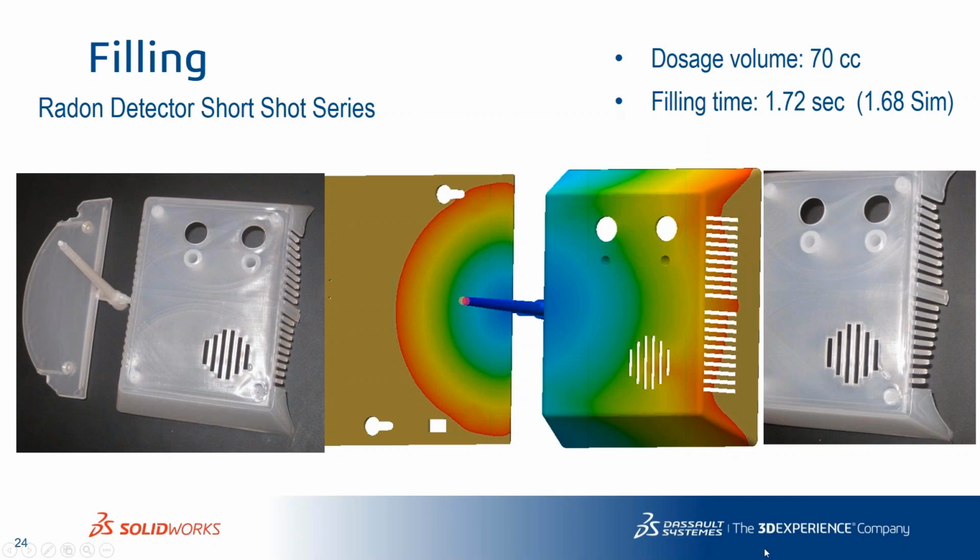You always have to think about, in terms of the software, it is built to fill the part, right? Its task is to fill the part, so it's going to try its best to fill the part. And if it's not filling the part, or even if it does fill graphically in the software but it's telling you it was very difficult to fill, there's actually a result that tells you how easy it is, called ease of fill. So if it says that it is very difficult to fill from a software perspective, then chances are in reality it's not going to fill all the way.